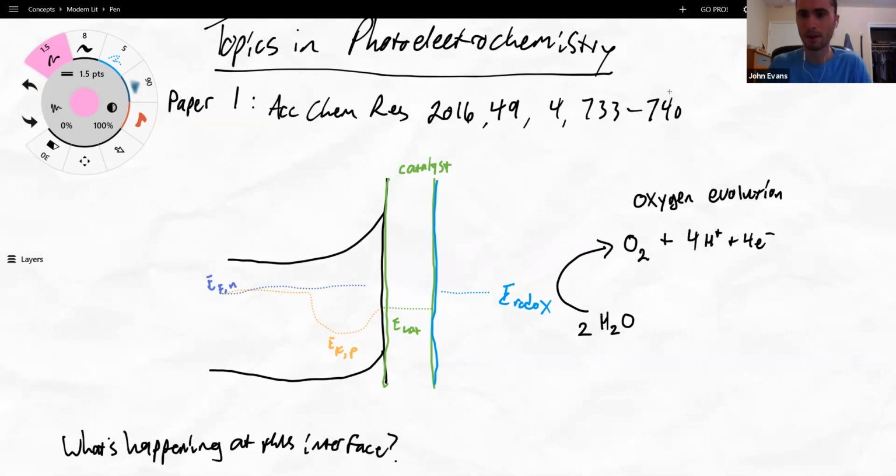Now, I mentioned this a little bit before in our recitation section, but a quasi-Fermi level is just a Fermi level that exists in a non-equilibrium condition. So normally you have two Fermi levels for electrons and holes that are just equivalent to one another. Under illumination, remember we had that analogy: we have a whole bunch of electrons and we add a little bit, and then we have just a little bit of holes and we add a little bit. And that's going to seriously change the concentration of holes on one side of this band, right? So what happens is the bands come down. Just the holes though, because remember the electrons aren't really affected all that much because there's a much higher concentration of them. So that stays right about where it's supposed to be.